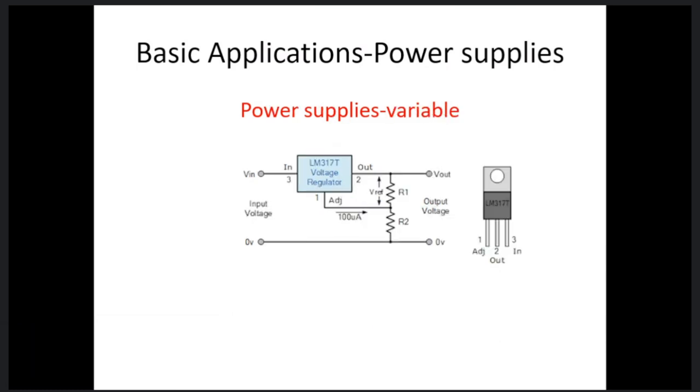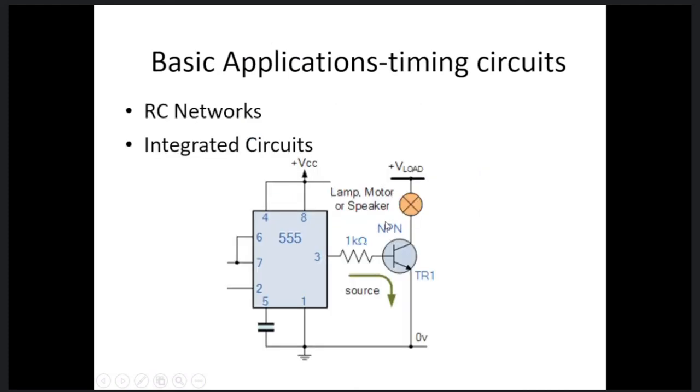So it's a variable regulator. Again here, LM317 is a variable regulator. And this is from the application schematic, a basic application schematic. This is how you have to connect it yourself. And for the output voltage, you have the proportion equation. It will give you this much voltage when you select the proper values of R1 and R2. Because it's a variable voltage regulator, not a fixed voltage. Earlier you saw 7805 is a fixed voltage, LM317 is a variable voltage regulator, and the varied voltage depends upon R1 and R2. So you get this information from the data sheet.